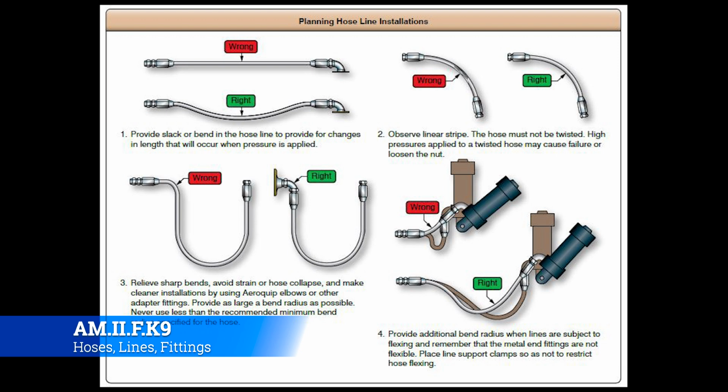This is something that I learned personally in the first couple of months of Iraq, because we had aircraft that hadn't been flown super hard for a long time, and a lot of people made these types of mistakes whenever they installed it. And so whenever we got over there and we started flying, 12 on, 12 off every day, a lot of pressure got put on these hydraulic lines in a way that it hadn't ever been before, and so they started to bust and explode and have all kinds of problems.